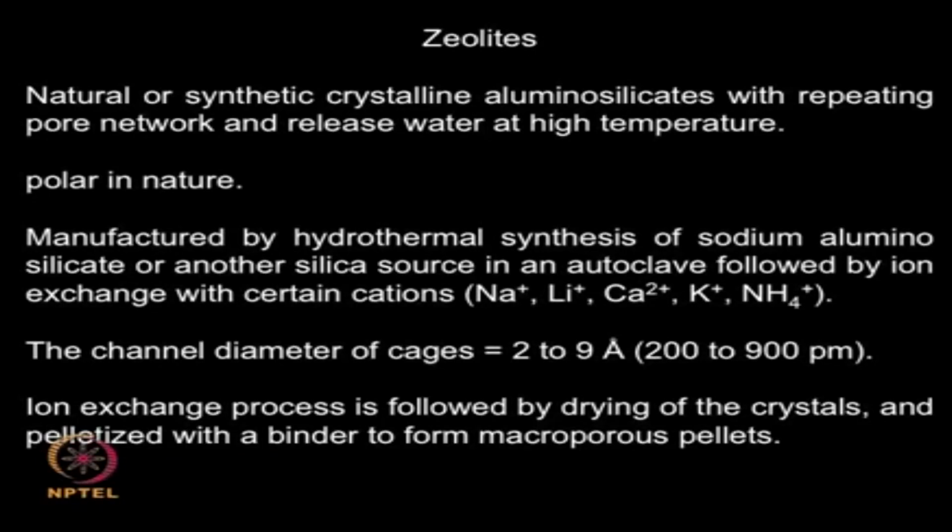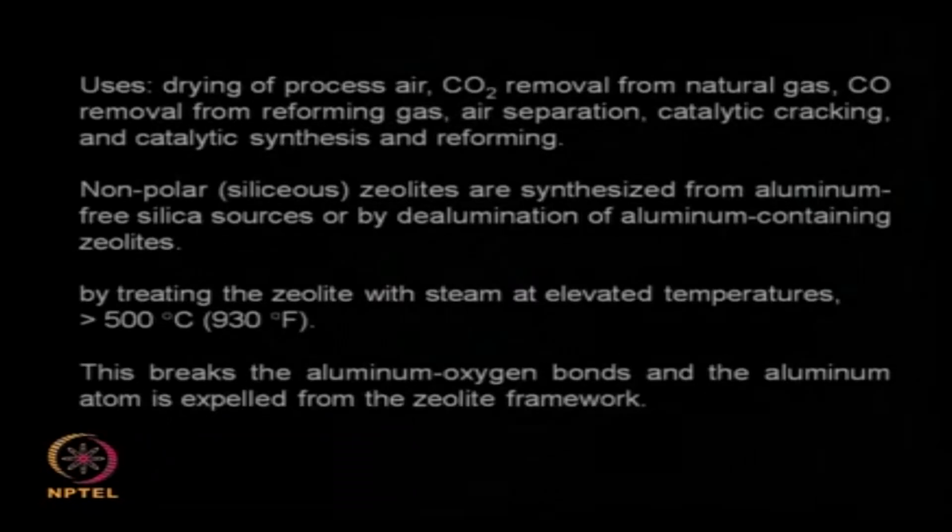So once you have prepared your zeolite using ion exchange, you go into drying, and then it goes into pelletization and binding to form macroporous pellets. Okay. So in a solid material, a solid adsorbent, there is always something called pelletization and binding, so that the adsorbent is mechanically stable and it has got a good shelf life as well. So zeolite is another adsorbent which is widely used nowadays for gases as well as for moisture removal.